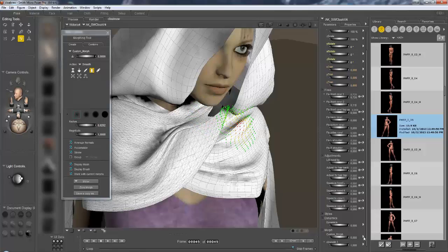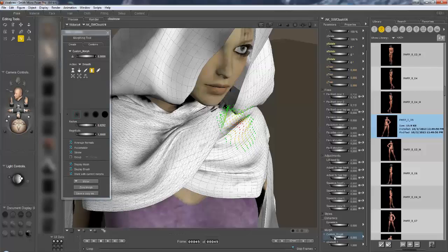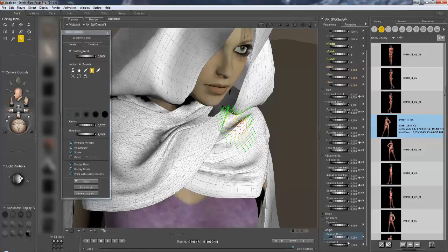I do not need it anymore, but this custom morph is the container for my fixed morph. When I dial it up to 1, you see I'm getting this crumpling. This is the old fixed morph I created before creating this new one, so it interferes with my new shape. And I can just delete this one. And when I apply the morph brush, I will get a new one, also named custom morph. But now, since it's set to value 1, it works.